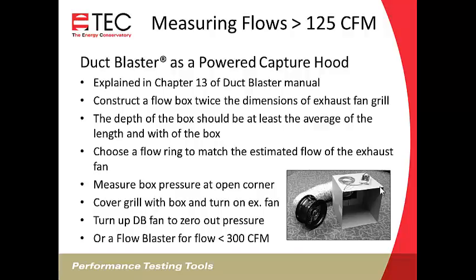Or we do have the flow blaster attachment for the Duct Blaster fan, which converts the Duct Blaster fan into a powered flow hood with a battery powered speed controller, and that device makes it easy to measure the flow through an exhaust fan up to 300 CFM. So that gives you more of a range if you've got the flow blaster attachment for the Duct Blaster fan.